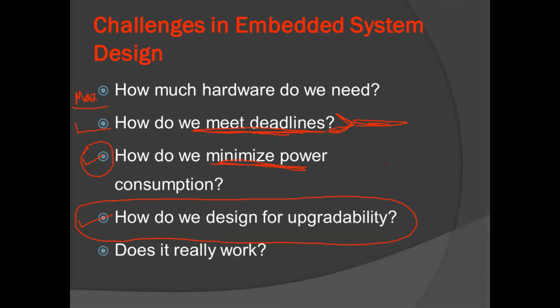The parameters that we are sensing, temperature and humidity, are very slow parameters that are almost constant over an hour, or almost constant over a 10 or 15 minute window. So we need not worry about the time criticalness of the system. So what we are going to do is make the clock frequency very low, so that it would utilize minimum power, right?